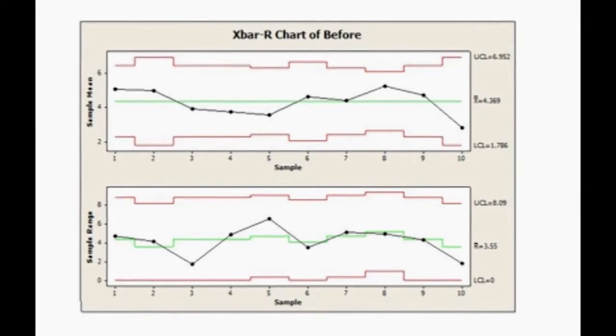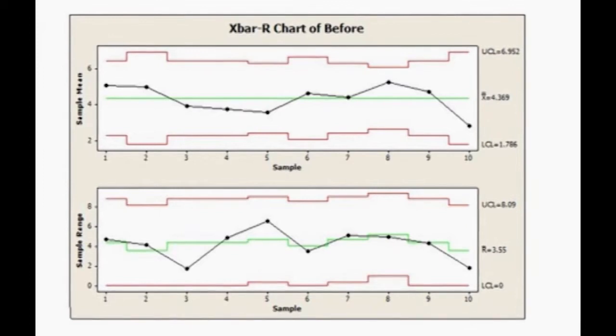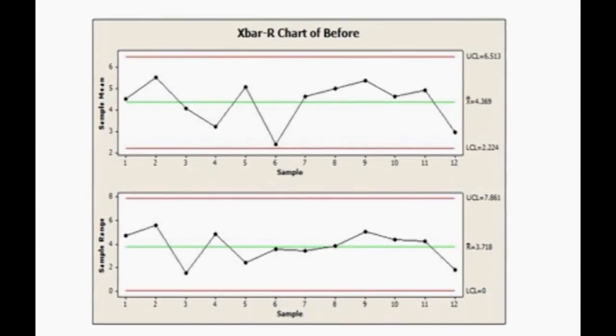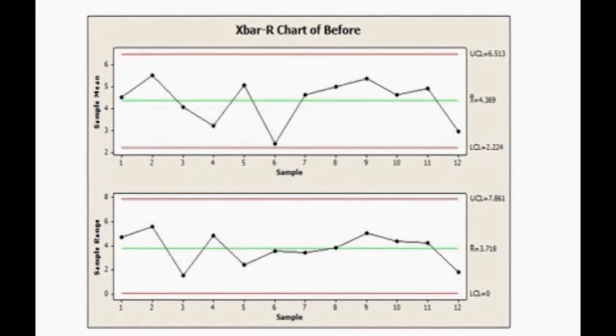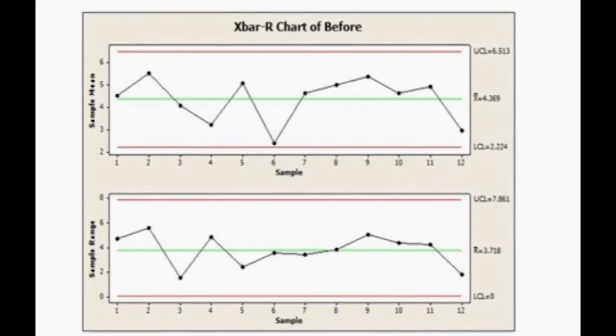Now, what you have to take away? The control chart X bar R is generated, and if you look at the control limits, they are varying because the subgroup size per subgroup, that is per agent, is varying. Now, X bar R with constant subgroup size for all subgroups. Look at the control chart below. If a subgroup size of 5 is entered in the subgroup size cell in Minitab, the control limits are in a straight line.